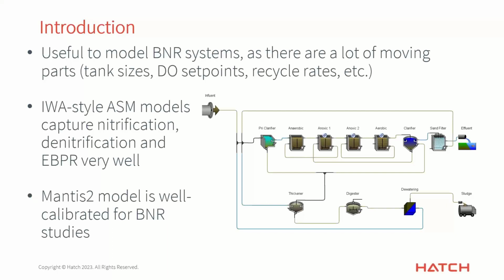I mean, that's exactly what they were designed to do. So those approaches have been tried and tested and well calibrated over the years to be able to accurately switch to different types of growth depending on what the conditions of the reactor are, whether it's anaerobic or anoxic, for example. And also we have a really good understanding now of what types of biomass are growing under what conditions and what the stoichiometry of those things are. So the models are really useful for doing that type of design.